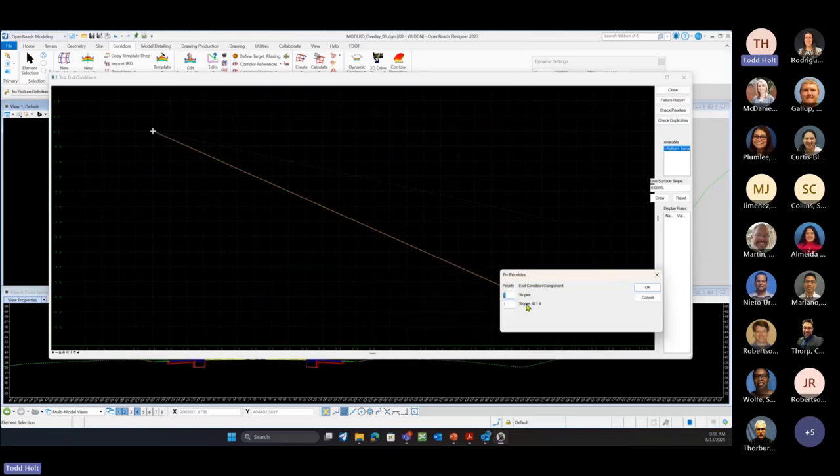And there we'll see there's our slopes. And if we toggle here, there's our fill slope. So which one do we want to solve first? Right, in order, because right now if we do this, it's going to try and draw both of those. So maybe that fill slope is 1, and we're going to set this to, we can go 2, we can go even numbers. It's just the order of which we want it to solve for.